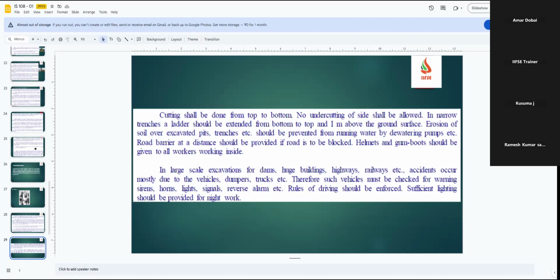He is a very good guy. He will follow everything. Then I talk about a machine. So I have to check my machine. Does my machine have all the safety controls? Does my man know about these safety controls, how I can operate? Or does this machine have auto cut-off controls if it is overloaded or exceeding high operations? All the guards of the machine should be properly in place.